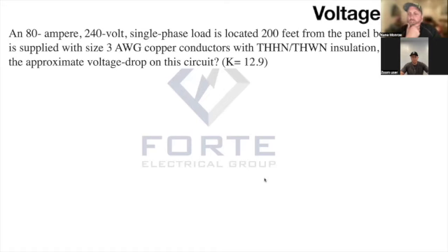Here's a question for you. An 80 ampere, 240 volt single phase load is located 200 feet from the panel board and is supplied by a number 3 copper conductor with THHN, THWN insulation. What is the approximate voltage drop on this circuit? And they give you the K value right there.